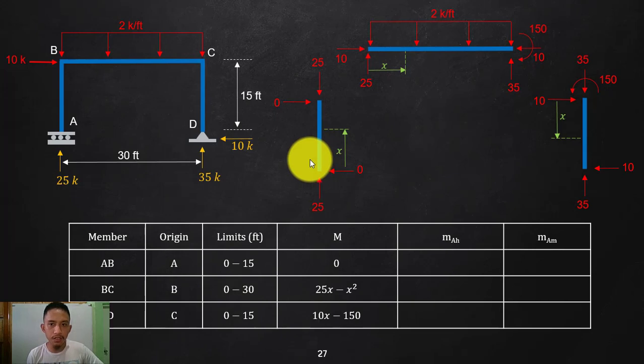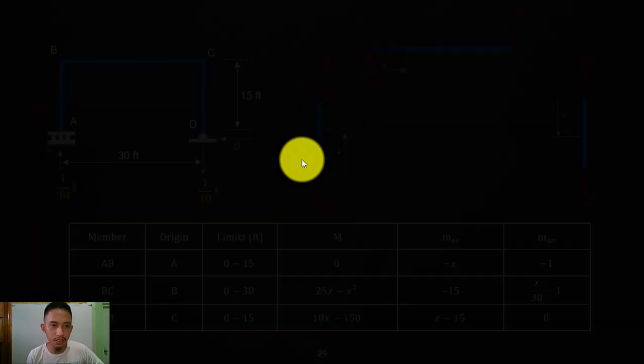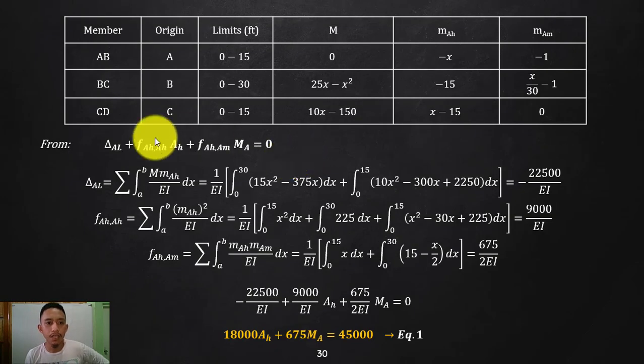Since there are two equations, we will be using one of these, but they should not be interchanged. Since we are talking about a deflection, what did I say? If it is a deflection you are after, you need to apply a force. So I need to use the virtual moment equation of the force. This is your force, isn't it?